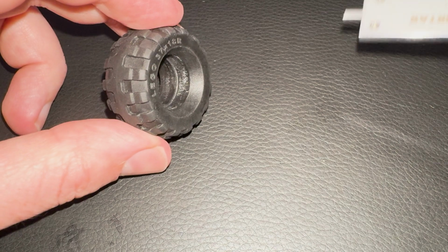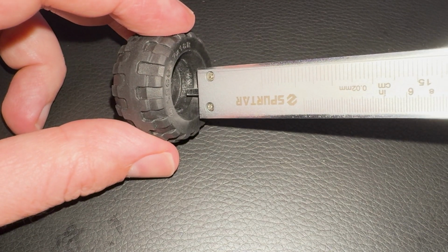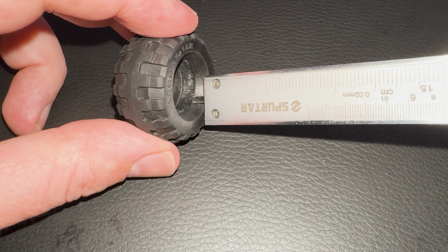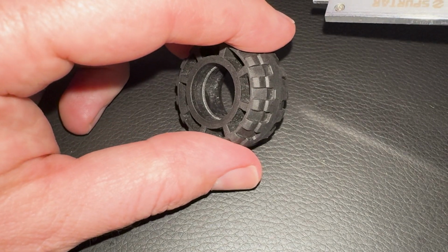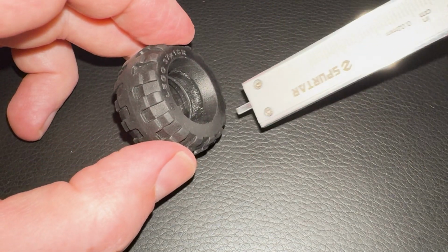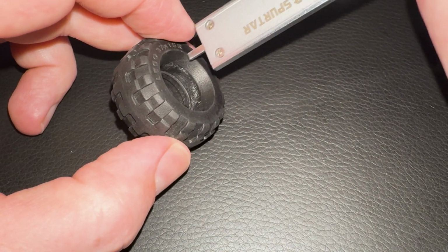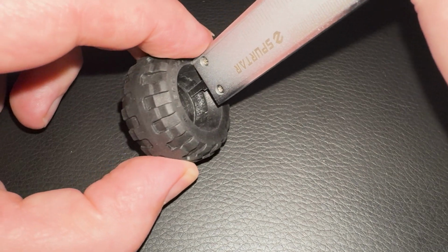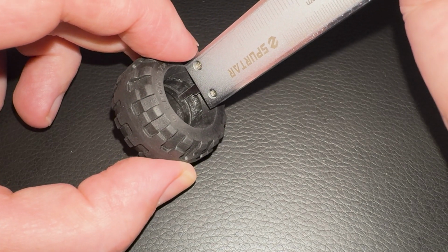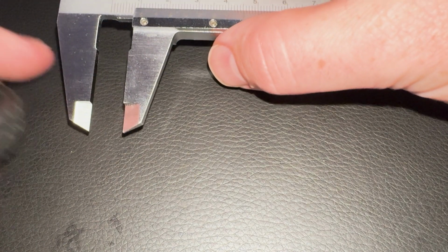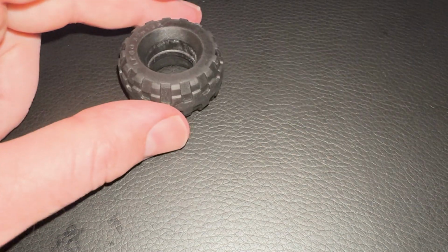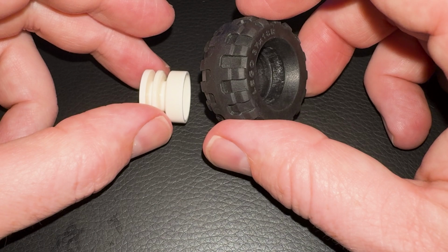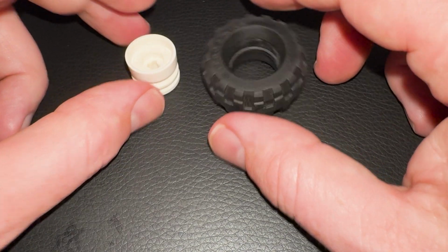If I'm looking from this view, it looks like it's the same distance, but not from this front face, it's from this edge of the chamfer. And I think that's where I made my mistake, because I put that chamfer on after detailing this product. So I think that edge actually sits from the front face maybe about 11 millimeters. So let's make that change in the CAD and see how that impacts our interference.